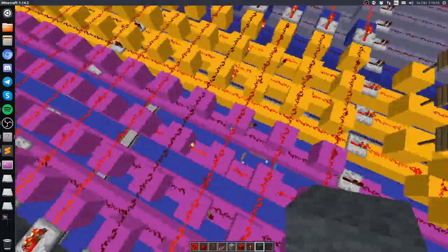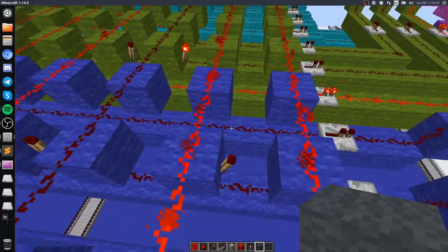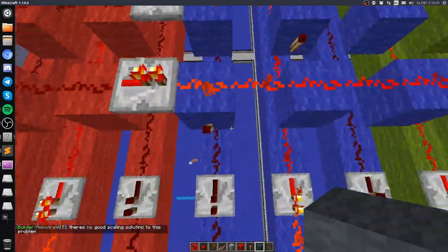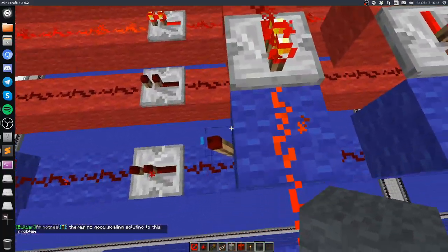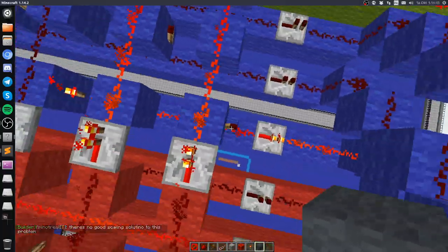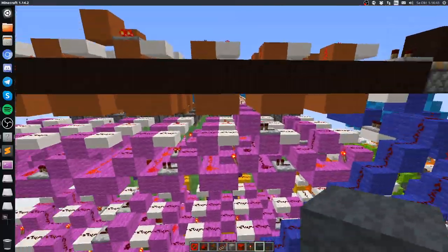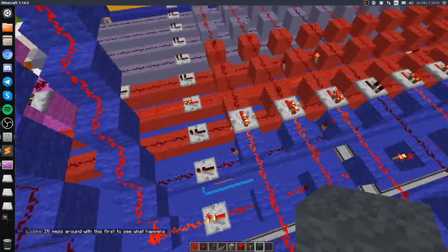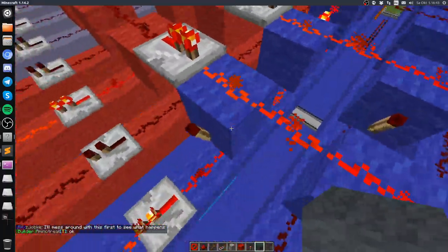So when you have this code here, you can see I'm using just register 1 and 2. And what I'm doing first is I set 0 into the first register. So you may say that's unnecessary because you could reset the whole CPU and then zeros everywhere. But I cannot expect that a CPU which is in a random state and got shut down has a 0 in the first register because it got reset at some point.